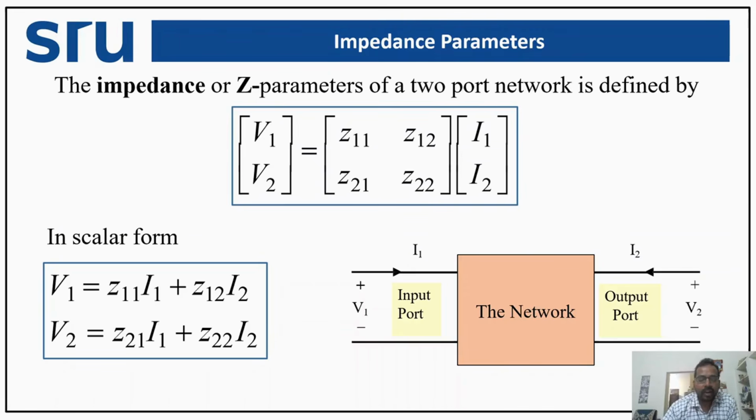Now, students, we have come to the heart of the lecture, which is the mathematical model of our impedance parameter. Up to this point, we have discussed what a two-port network is and why we need this particular parameter representation. Now, we are going to formally express the relationship between the voltages and currents in such a network. The fundamental idea behind the Z parameter is that the voltages at the ports are expressed in terms of the currents. In other words, the port voltages are treated as dependent variables and the port currents are treated as independent variables. This leads to the following mathematical relationship.